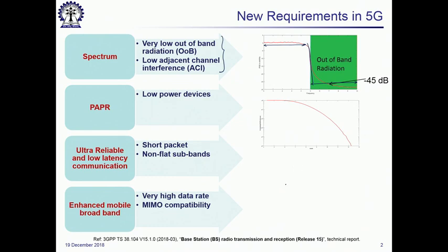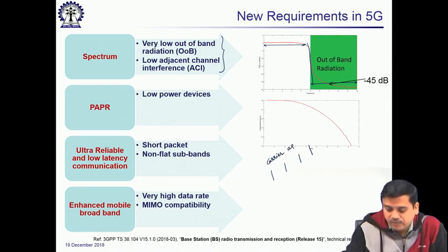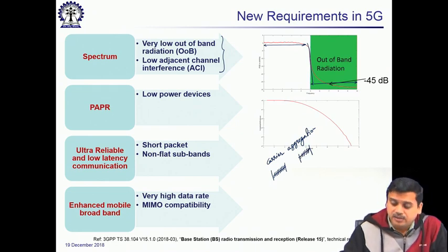And this is very important, because what we have not discussed in great detail, but what we have seen, is that separate bandwidths can be allocated, and there is a very important part which is called carrier aggregation, which we are not discussing here. In carrier aggregation, suppose there is a certain band of frequencies available and a particular service is operating in that, and another band of frequency is available and a service is operating in that. These two bands could be aggregated to provide the same kind of service.